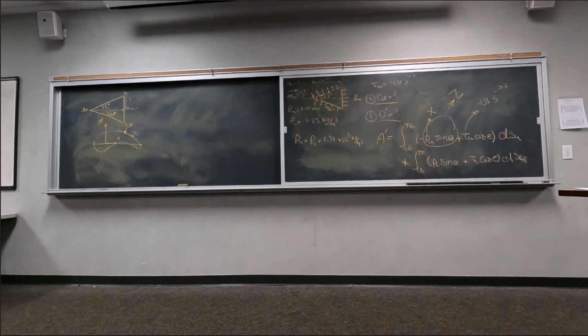It will cancel out lift, that's correct. But it doesn't cancel out drag though. So how do we get drag? That's the idea. Lift and drag are perpendicular and tangential to the flow direction, right? Axial and normal force are perpendicular and tangential to the chord, right? What will happen to those forces when the chord and flow direction are essentially the same direction?